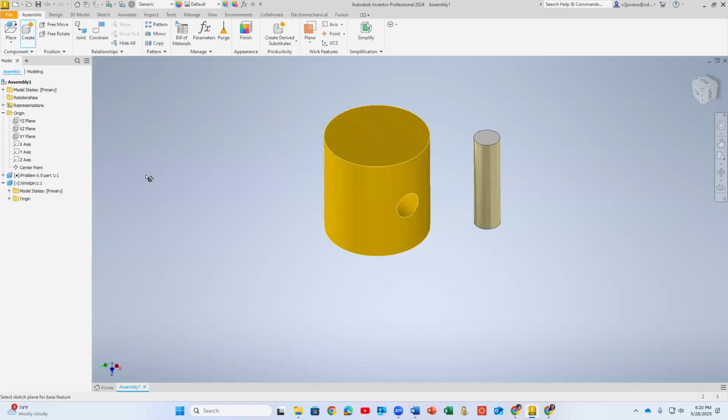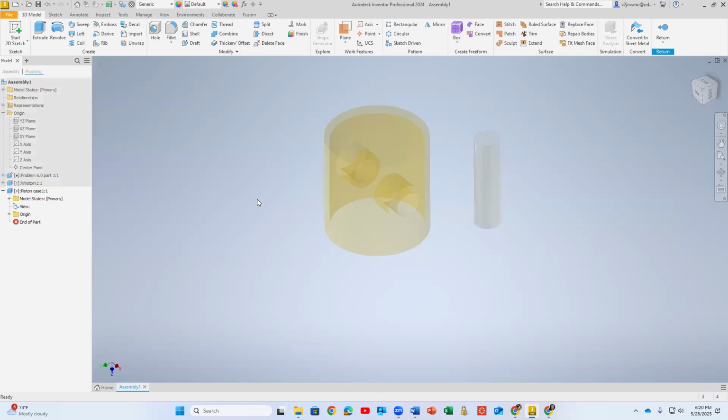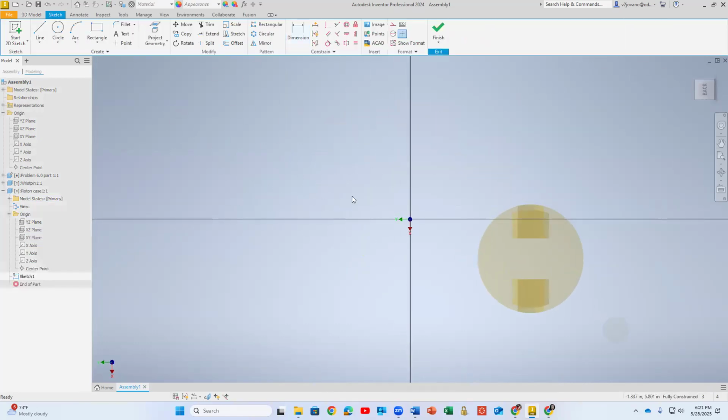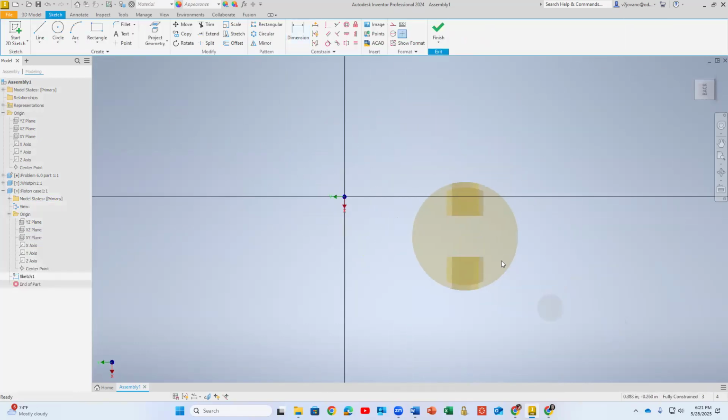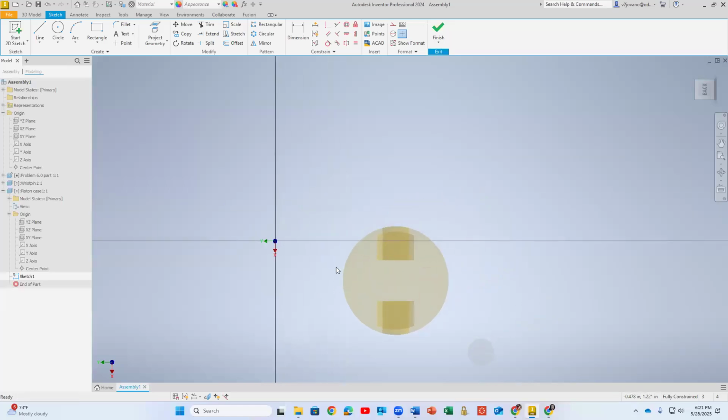Okay, and then I click somewhere because I still don't have a location for it. So they would like to do a sketch. Well, they didn't say where, so it really doesn't matter which one I want to do. So I would say maybe XY plane, right click, create new sketch. And I don't worry what is there. I'm just looking at what I need to draw. You see they were driving it a little bit around, but I really like to use the coordinate system and to have fully constrained sketches.